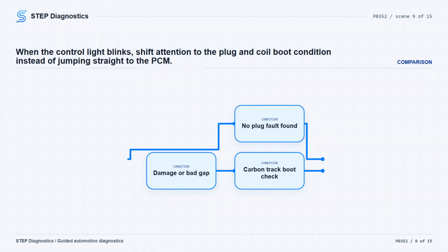If the control circuit is brightly blinking, turn the ignition off and remove the spark plug or plugs using the correct removal procedure. Inspect for cracks, carbon tracking, foreign material, gap size out of specification, and any loose or broken electrode.